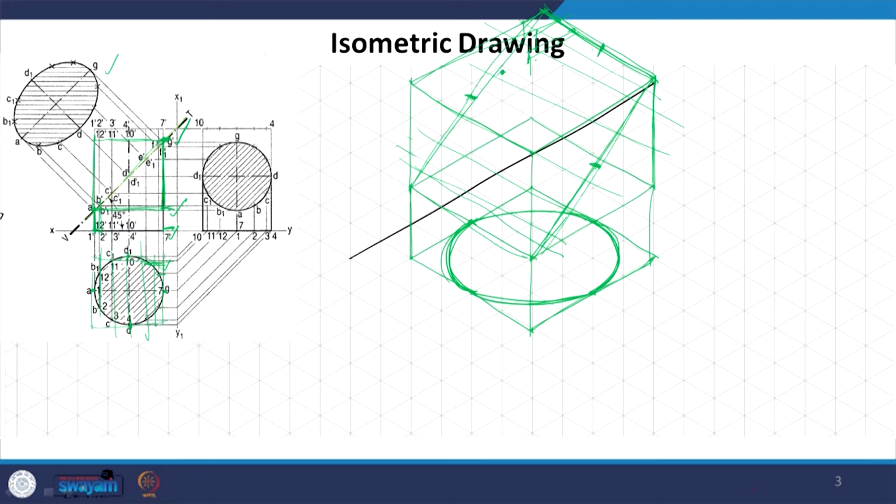I am not exactly getting at these points, but this is how you will be arriving at these 12 points in which we divided the circle. Okay. So, this is the isometric projection of this ellipse, which is what we are going to get on this plane. Every time we are making these drawings, all we are doing is identifying the planes which are cutting the original solid, or where this inclined plane is being contained. Now, we already have this final drawing, so we will just join.